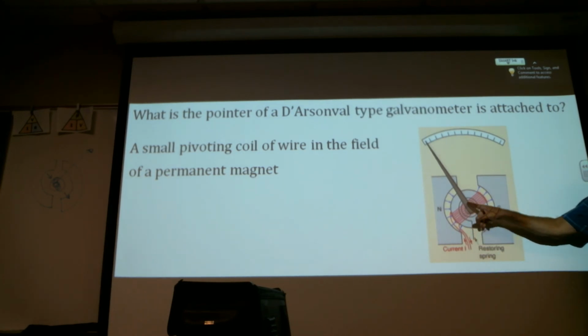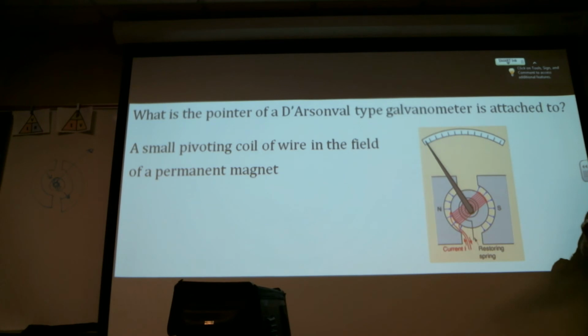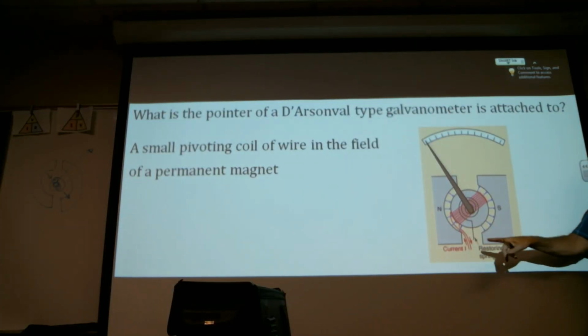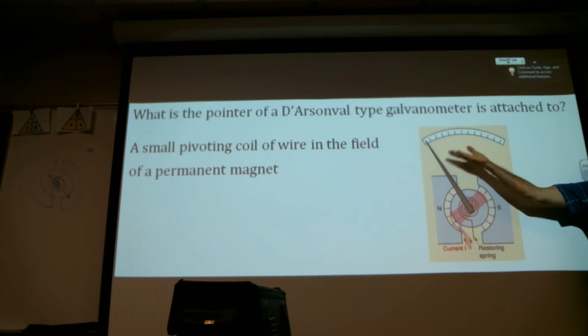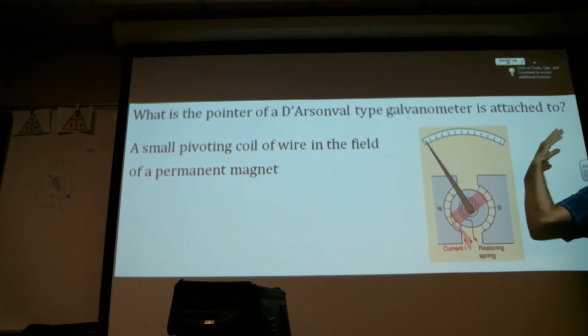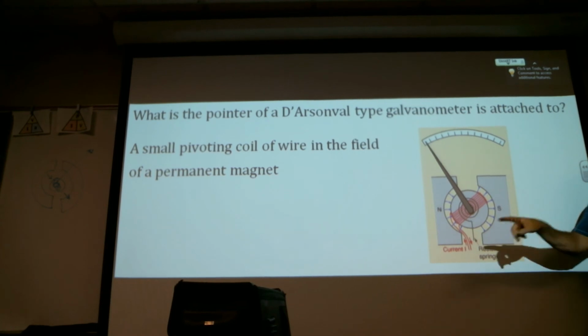So whatever goes through these red coils will always be the same, because all you have is magnets, a spring, and a coil, no matter what you're measuring. So it's the selectors that we make on the meter that determine how much goes in. Do you have one you can take apart? Don't think so, but I can very easily pull up Google Images and show you one that's apart. That's why, if it slams hard, it's because you've got the wrong selection and you're letting more current in there than you should be.